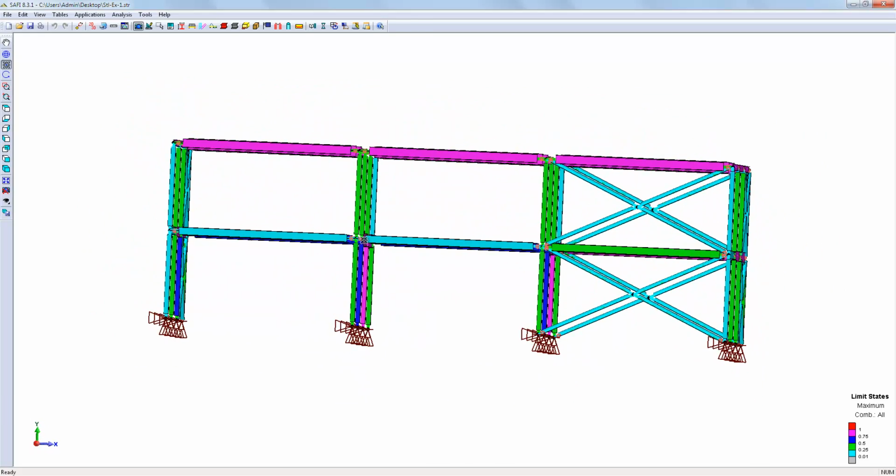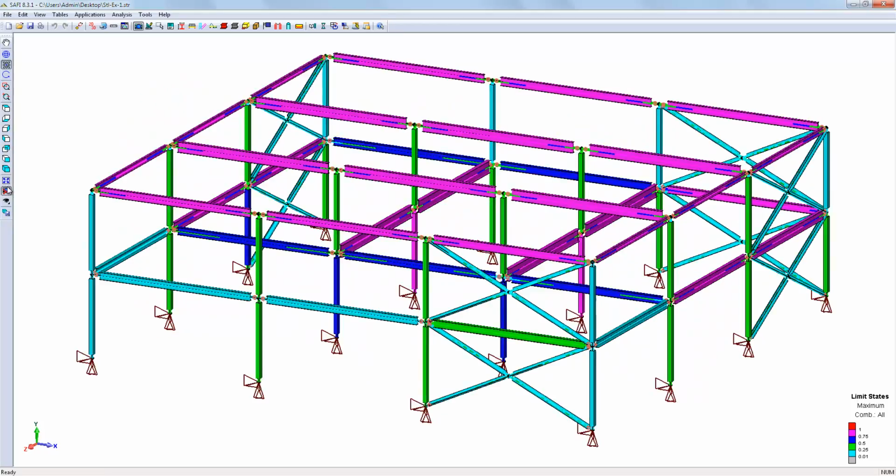The Orbit command is restrained by the screen's X and Y axes. The rotation around the screen's Z axis is made with the Roll command. To make a rotation around the geometric center of the structure, use the Rotate command. To set the rotation around a particular axis, screen's X and Y, click with the right button of the mouse on the structure and select the desired option. The current option is marked with a check. To exit the command, use the Escape button on your keyboard.